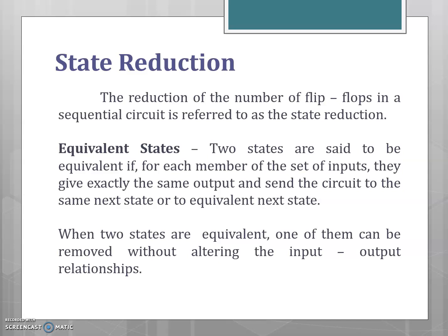We'll define equivalent states. Two states are said to be equivalent if for each possible input they give exactly the same output and they go to the same next state or to an equivalent next state. So when two states are equivalent, one of them can be removed.